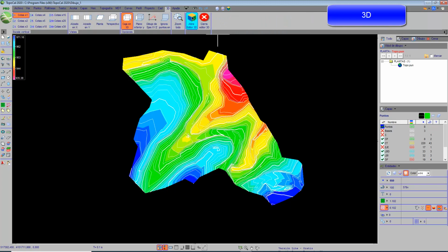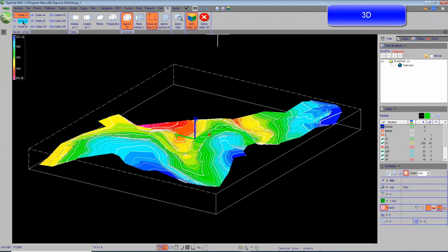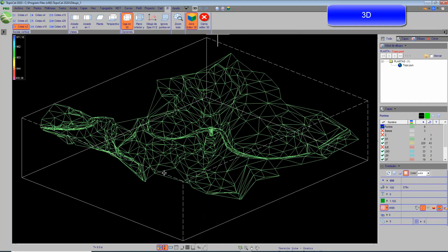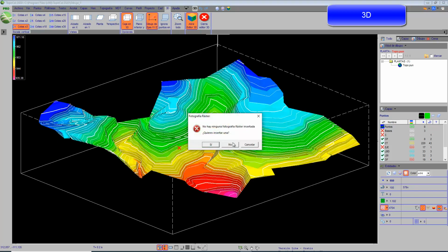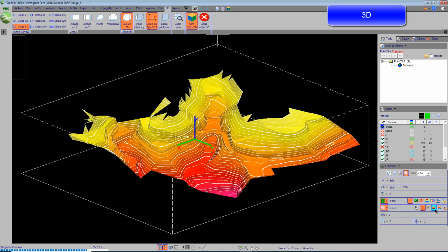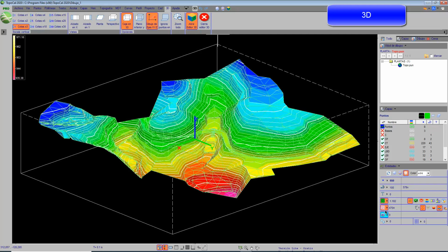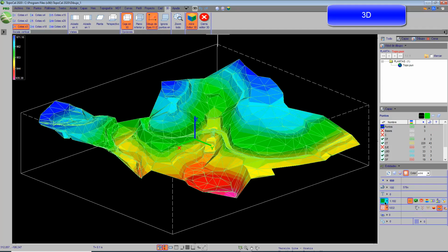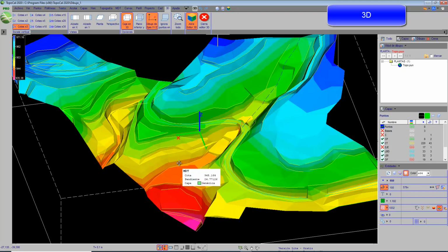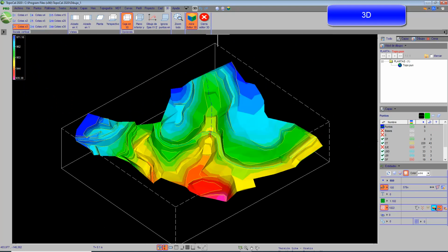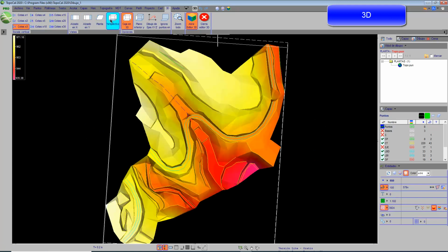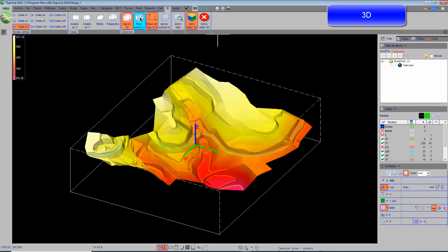3D vision. We can see a 3D representation of the terrain. By default, it does it in gradient green depending on the slope of each triangle. A higher slope makes greater color intensity, and a lower slope sets a less intense green. We also have the options to do it in gradient red color or by colors. We directly have the land in 3D.